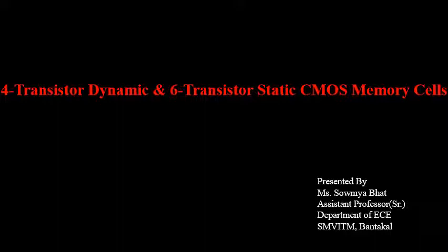So in case of dynamic memory cell, you are going to perform the periodic refresh operation, whereas in pseudo static CMOS, we have considered one more additional transistor applied with the clock signal of phi 2, which is going to perform the refresh operation by itself when you finish the write operation. So now let us discuss the concept of both dynamic as well as static memory cell in terms of 4 transistor as well as 6 transistor.